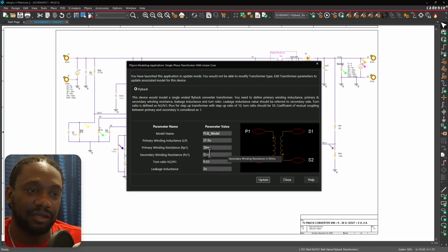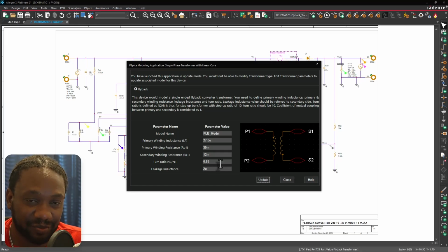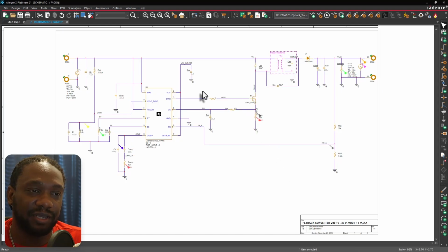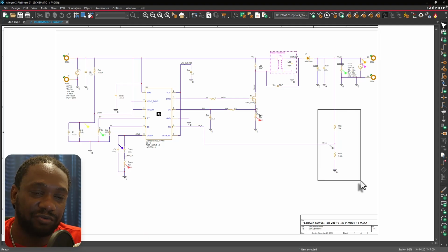Because if the windings give too much responsibility, so to speak, or energy to the primary side or to the secondary side, particularly the primary side, then that means my duty cycle could only get to a maximum amount of duty cycle, say 47%, 50%, which would limit the amount of energy you can dump into the transformer and then release once the switch is turned off. Most likely, though, it's the sizing of these output resistors, right?